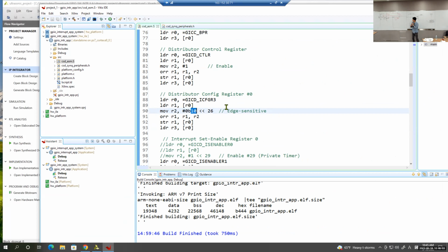So I did some experimentation. If you change that to edge sensitive and you do not clear this bit in the ISR, then the interrupt is not generated again. It is generated only one time when you push up. Even though you push down, there is no interrupt generation because the status register still contains that bit. You didn't clear it. So this line is fluctuating, going up and down, but the interrupt line from the GPIO stays high even if you don't clear.